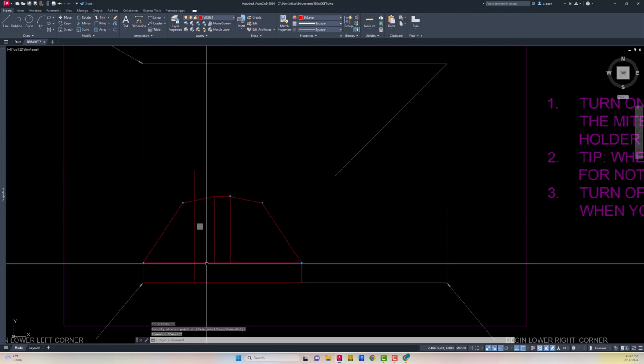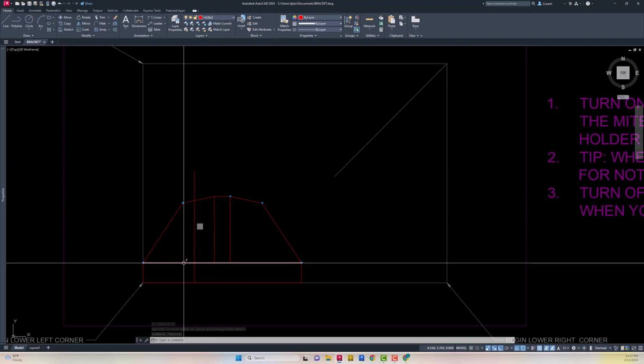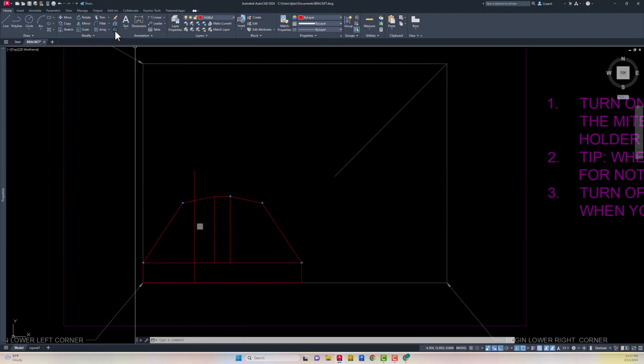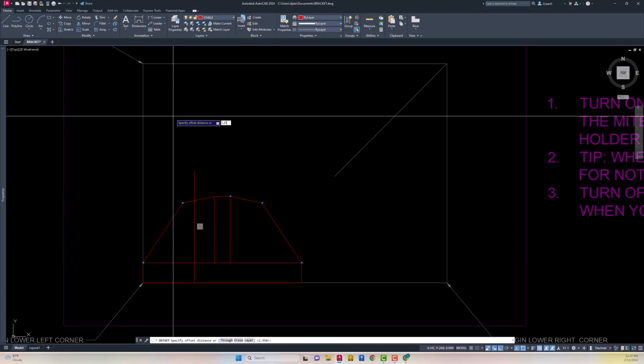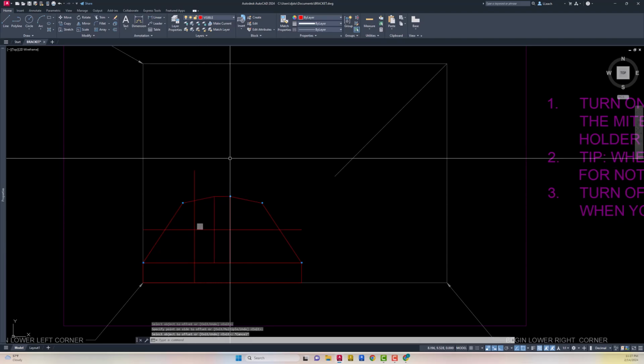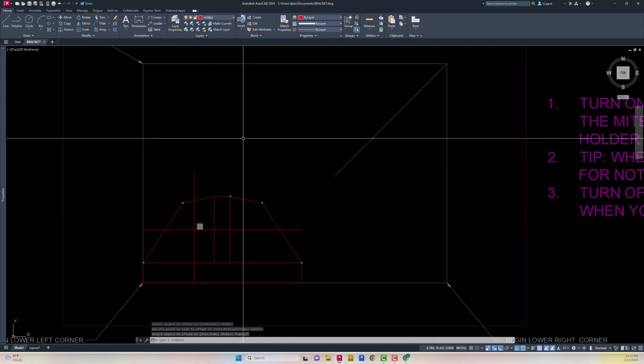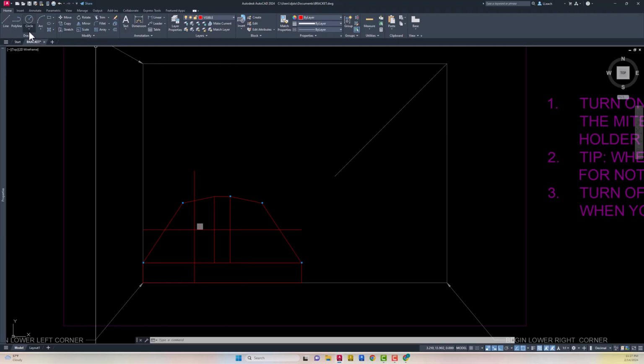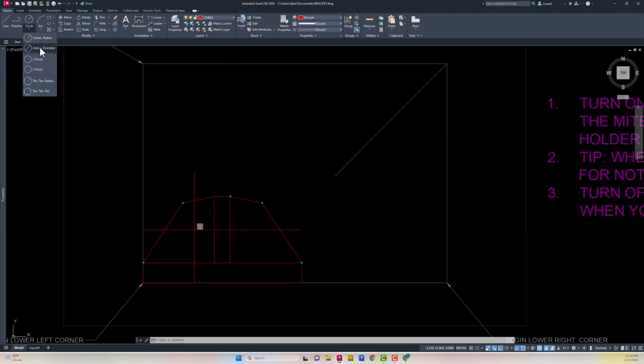And it's going to be offset from this line here up by 1.25. I'm going to offset 1.25 this line up. And so that's our location for the center of our circle. And I know that that circle has, I'm old and blind here, it's 2 times 0.625 for the diameter. So the diameter is going to be, I'm going to make a circle with the center diameter option.